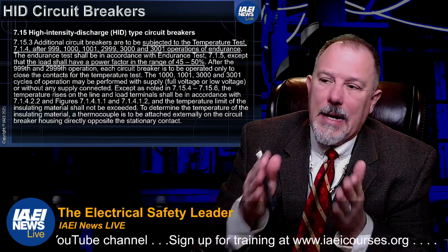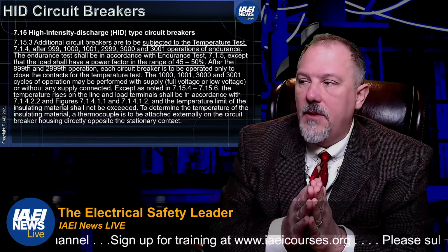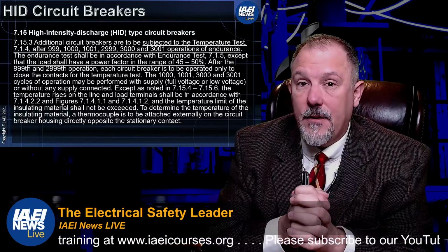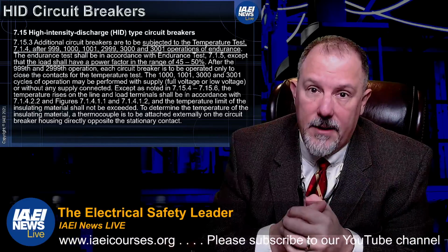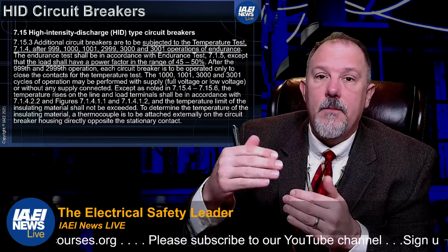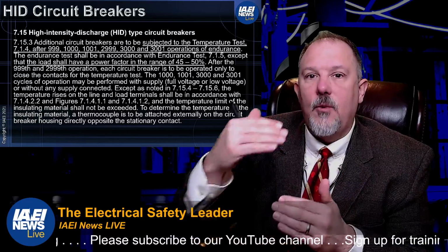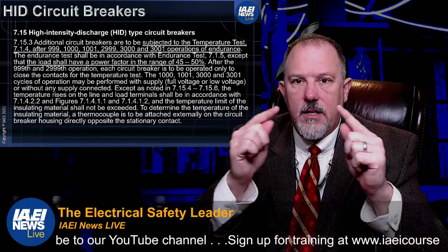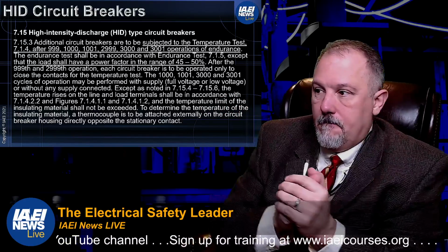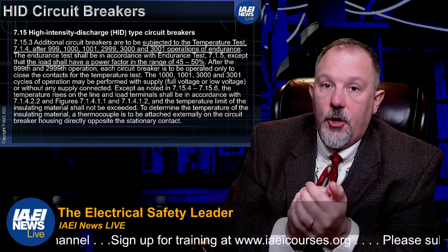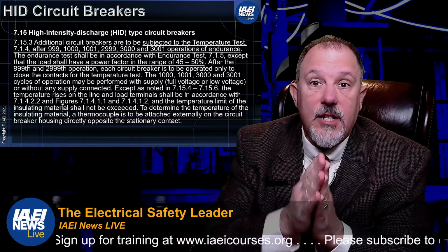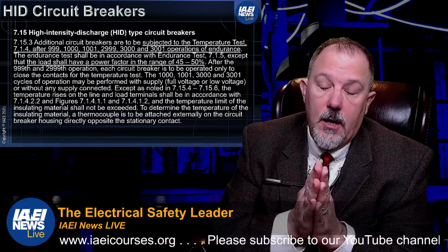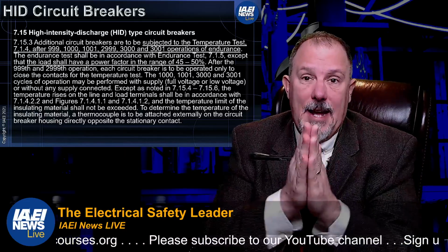So what I might do differently, maybe the contacts on the surface, the materials that I use might be different. I'm not saying that that is a fact, but I'm just thinking from understanding the physics, understanding what is going on in the separation of those contacts and the arcs that we're drawing. You want to make sure you don't degrade the contacts. What are the things that circuit breaker manufacturers want to avoid? Or any manufacturer of a contact device.